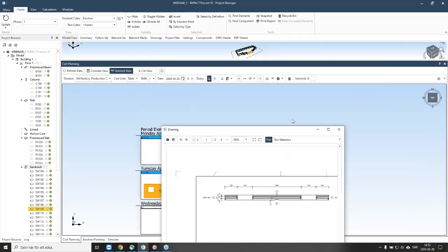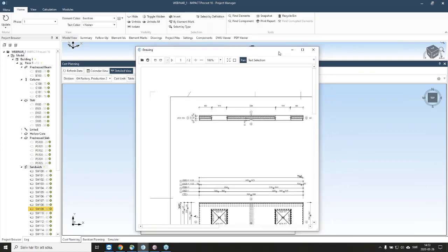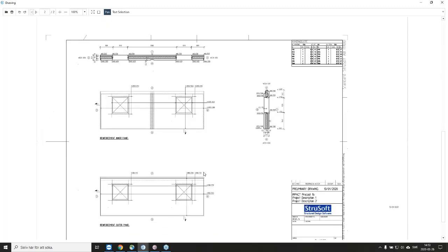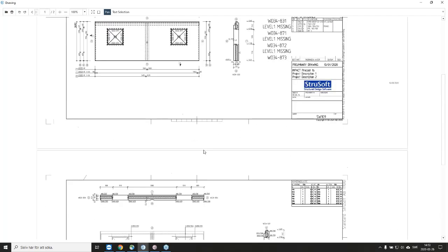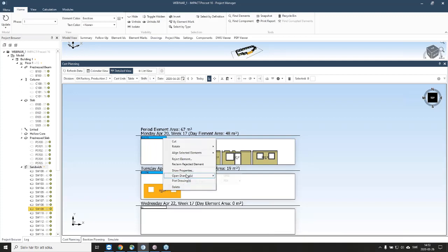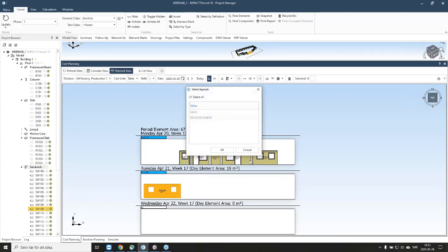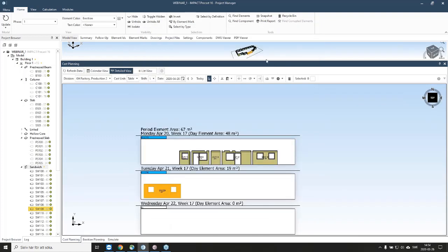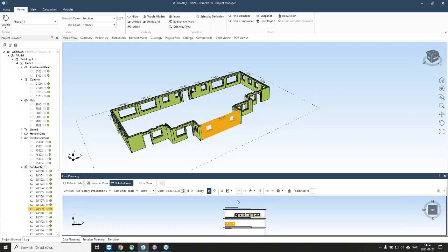And also now you can open up inside our internal viewer the blueprint. Maybe there's something that you wanted to check on that wall that you had to replan. Maybe there was a reason for the replan and you wanted to check the drawing again. So it's very easy. You just right click it, open the drawing. You can actually even open the DWG straight into AutoCAD or the PDF, and you can get it in your internal viewer. And you can even select the different layouts. Yeah. That is just great.